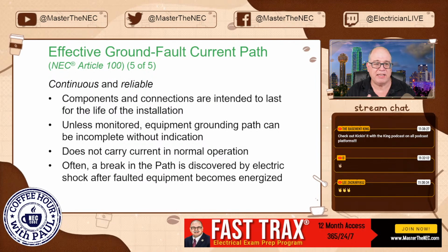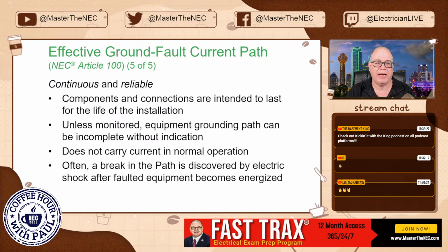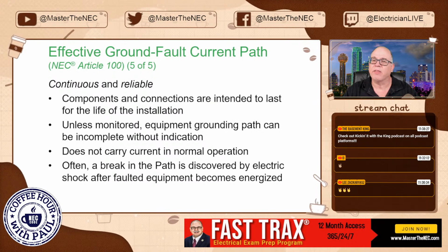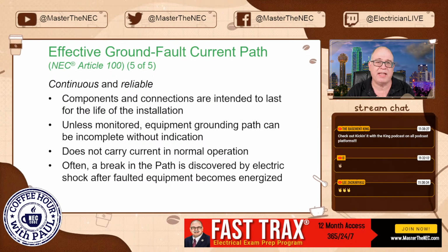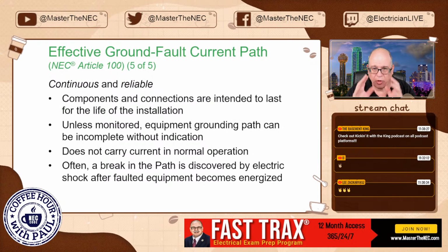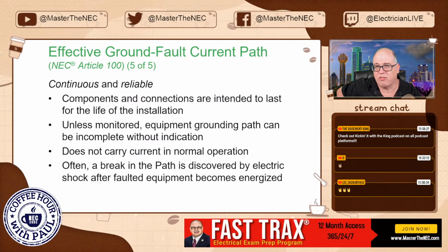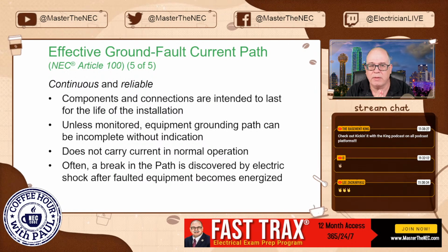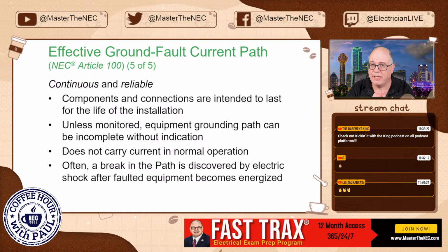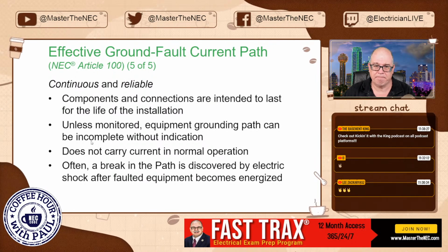It's not expected that you're going to come back and check them, even though a lot of commercial applications do annual torquing and checking. The concept here is that when you do it, it's a one and done. So put that wiring system in so that you know it's done. Tighten everything, wrench tight, do what it says, make those terminations, torque it, do everything that you need to do to make sure that you're doing it right, because it's for the life of the installation. Okay?